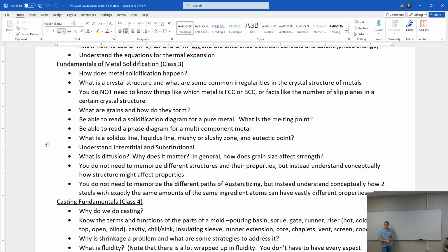So it's the amount of energy, it would be joules, because it's the amount of energy that something can absorb before it fails. So, yes, it is the area under the stress strain curve. So you have a stress strain curve. It's a plastic part, I take no responsibility for that. That area under there, up to the failure point.